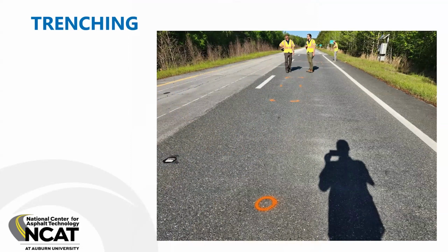And so finally, like Buzz mentioned, we've both been down in the trenches, and like he said, this is literal. That was pun intended. So here we are marking the location of some trenches just about a month ago from a failed section that's coming out on the track. And so we've got this longitudinal trench marked, and what you notice is this left side right here runs right down the middle of the left wheel path, and that's by design, because we want to catch on this cut face the inside, or the worst part of this transverse cracking here.